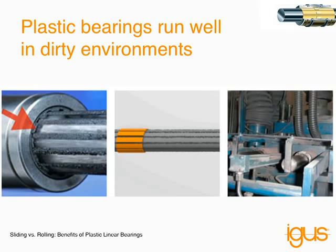We've kind of stated this a couple times in the webinar, but we get a lot of phone calls from customers who are using ball bearings. Maybe they're only lasting a month or 2 months, or sometimes even days, where the lubricants are being embedded with particulates and causing failure in the system. Plastic bearings don't have that problem because they're running dry. They work really well in dirty environments. They're able to wipe clean their shaft as they pull. They have dirt channels to enhance their performance, and a lot of problems can be solved by using these types of technologies.